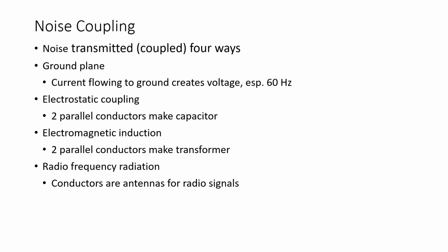For the EEG field, this is not so troublesome because these radio signals are in the hundreds of megahertz, so they're generally not that problematic for gathering low frequency information from the EEG leads. But understand that we will almost always have some high frequency energy present in our system due to radio signals, not only from the hospital but from nearby radio transmitters.